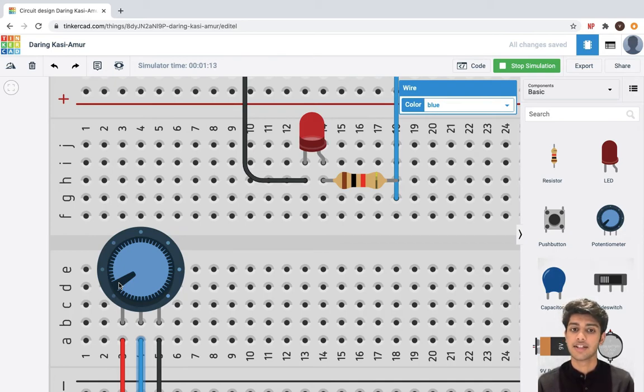And with this we come to the end of our section where we have discussed Arduino programming, the analog read and write function, and the PWM feature, which is available on the Arduino Uno in the form of 6 pins. So please do remember these pins. They are digital pin numbers 3, 5, 6, 9, 10, 11. Because if we interface it with some other pin, let's say pin number 2, this feature will not work as they do not have PWM functionality.